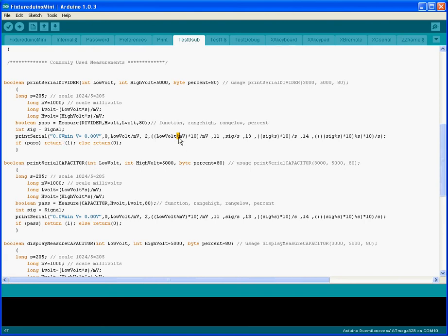This is what the modulus function was originally designed to be used for, is to take integers and make them look like floating points. Back in the old days before there was good floating point math available. So they used modulus this way. And the reason we're doing it is mostly just so that we can control where this decimal point is. So it's not floating all around in different places and making the LCD flash all over.